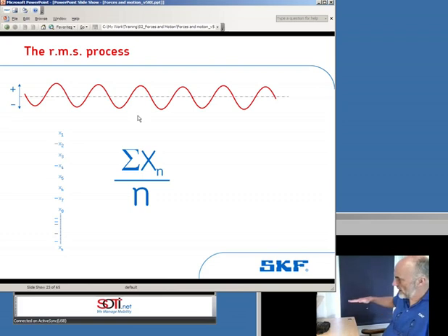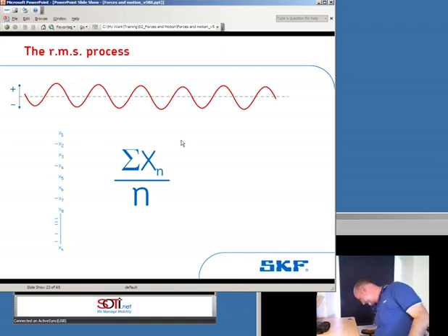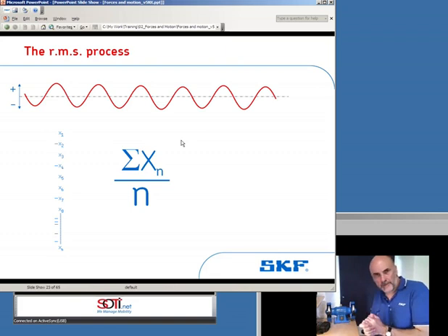Or going back to our dial test indicator and you're measuring the movement, the needle's going to go positive and then negative. So for something that's oscillating sinusoidally, you're going to get an equal split, 50-50 split between the positive and negative numbers. So when you take the average of these, the average position of this pendulum is in the middle, no vibration. So you say to your customer, this workshop grinder has absolutely no vibration on it. Wonderful, we'll buy 5,000. Wrong, this is slightly flawed.